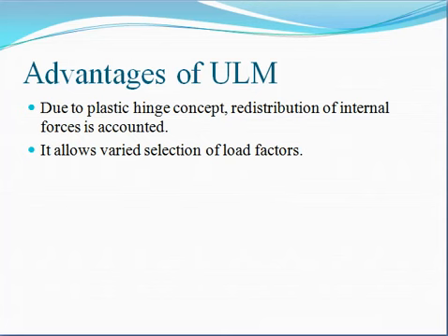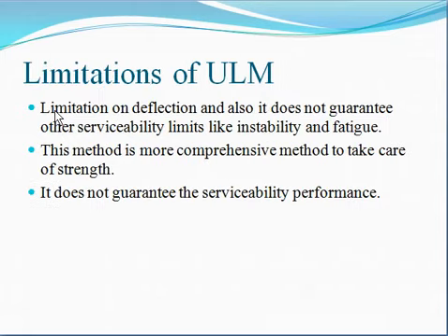Now we will see the limitation of the ultimate load method. The first limitation is limitation on deflection, and also it does not guarantee the other serviceability limits like instability and fatigue.